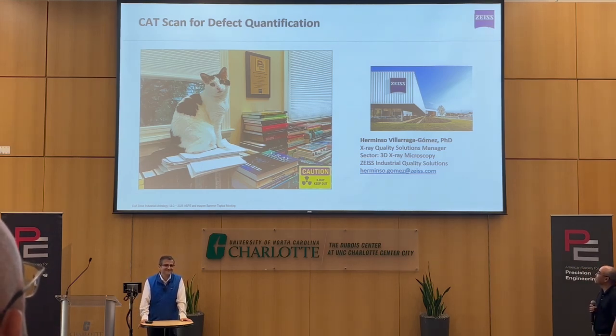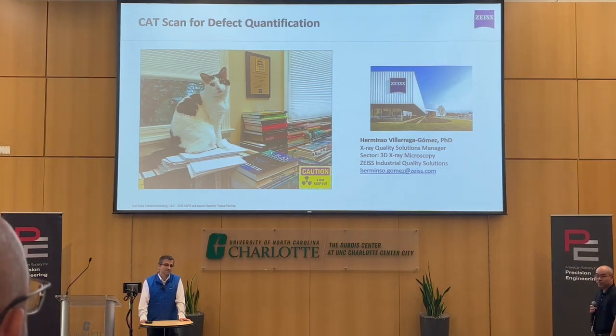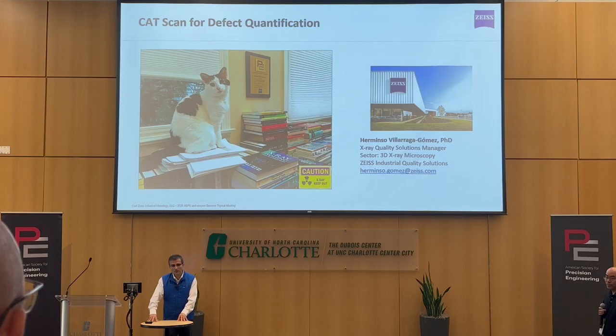So, in 2014, I had a paper with Zeiss, Mars and Pausa at the time, and we were looking at using CT for looking for both pores and also geometric defects. And we were very concerned about beam hardening with thicker pieces, but instead we defaulted to using lattice structures as the demonstration to avoid the beam hardening concepts. And I'm still seeing a lot of examples with lattice structures. Can you elaborate over the last 14 years, how far have we gone to looking for defects and understanding the uncertainty of finding those defects with thicker parts?